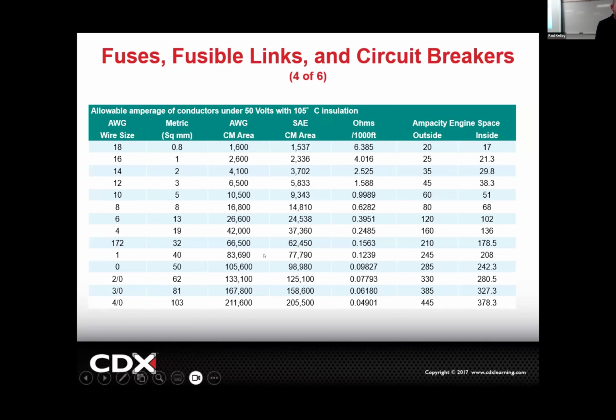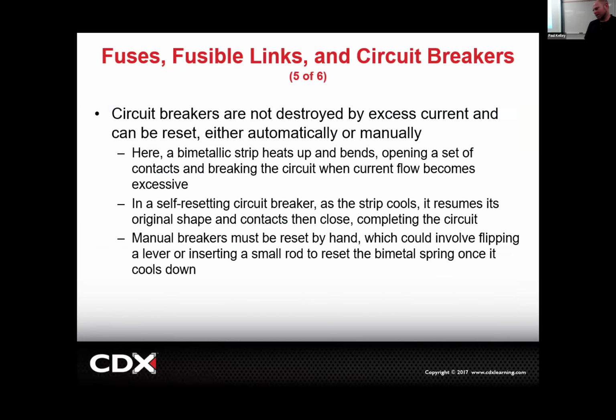So that's just your ampacity chart. And again, I jumped on Google real quick and I pulled one. Some of those numbers didn't make total sense to me, so it depends on exactly what you're getting. If any of you are going to be custom electrical engineers, a lot of times there will be an ampacity chart for the specific wire you buy that has a specific type of insulation and these other little details, right? So use that one as a reference point. It was true for whatever I looked up when I Googled that, but it does vary.